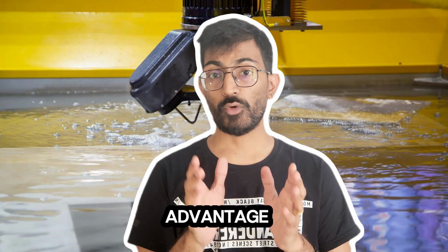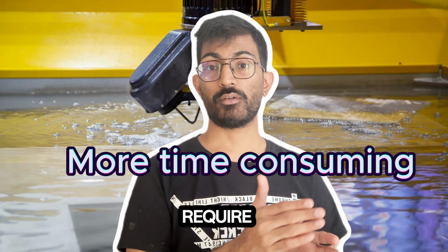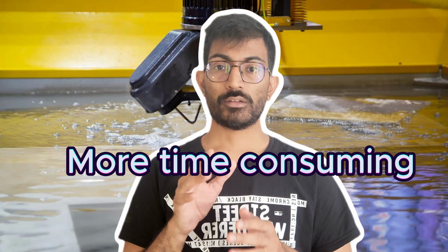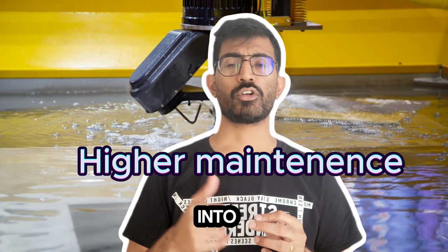The disadvantages of using the waterjet cutter for sheet metal, especially for thin metal, is that the time it requires to cut those sheets is 10 times the time required using the other methods. If the operator doesn't know how to maintain the machine properly, it runs into a lot of troubles.